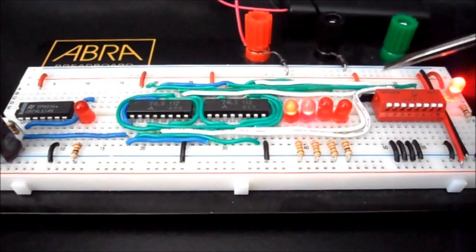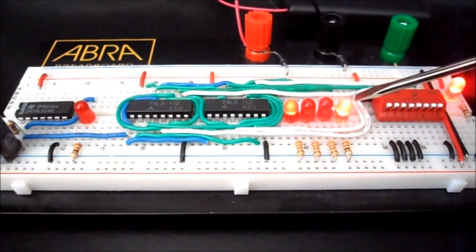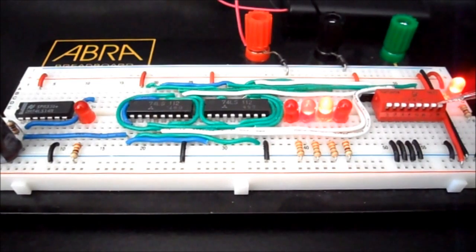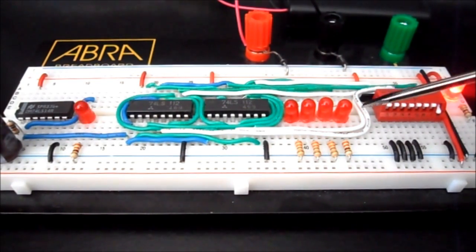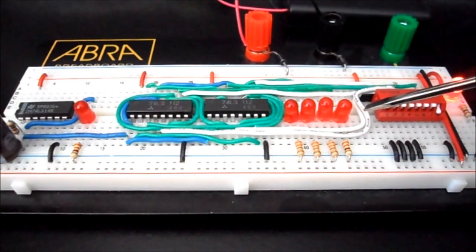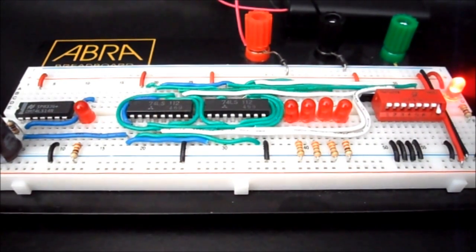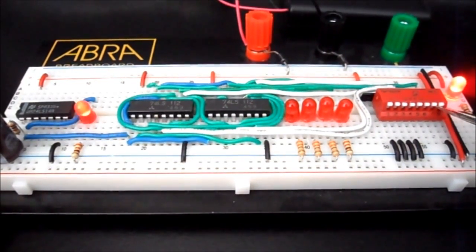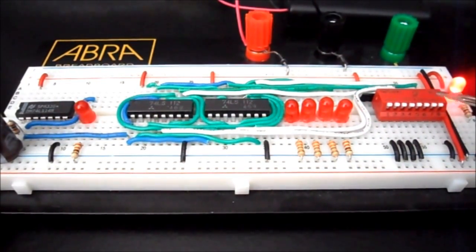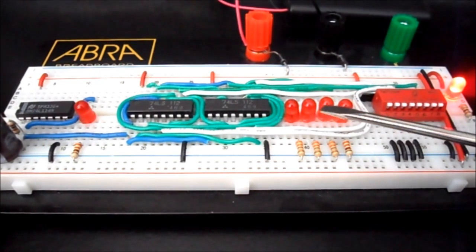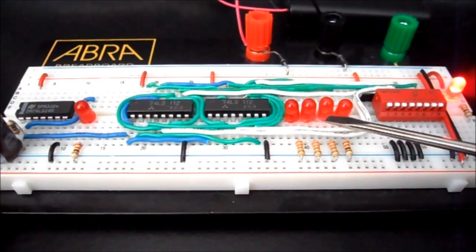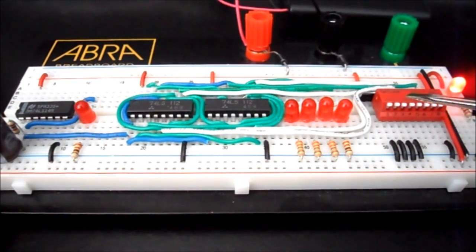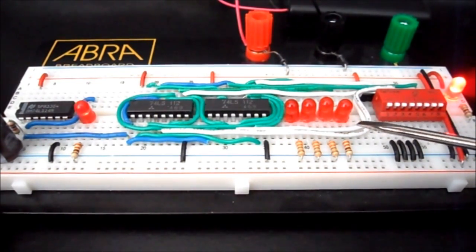So powering on the circuit, you never know what state it's going to start in. So you should start by clearing all your bits. So that's all my bits cleared. Then move your clear bit back up to logic 1. Now our preset lines, you have to move them fairly quickly because we've got a 1 Hz signal coming in, and if you keep the switch down too long, it'll just keep feeding ones straight into our circuit.